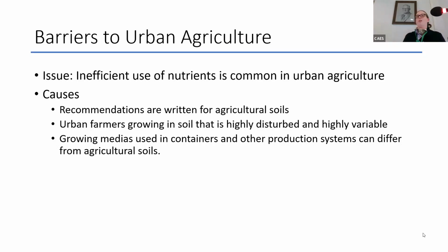And then there's also photovoltaics. Ornamental green roofs and photovoltaics go well together. There's a synergy there where the green roof helps keep the temperature within optimum range for photovoltaics, and the photovoltaics create more microenvironments for the green roof ecosystem. But you can't necessarily grow kale under the photovoltaics, although there's research looking into that now.